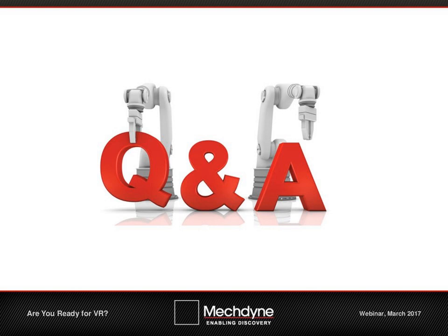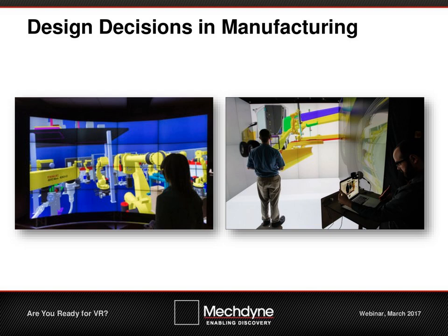It's not so much converting, or what we call tessellating, to simplify the file. It's more like removing parts that aren't going to be seen anyway. So if your model contains all the internal details of the engine, and yet you're interested in the structure and the body, then there's really no need to include that in the visualization. In other words, that is just weight to the model that you really don't need. So rather than spend time simplifying the geometry, we tend to strip out geometry that's not needed for the simulation.